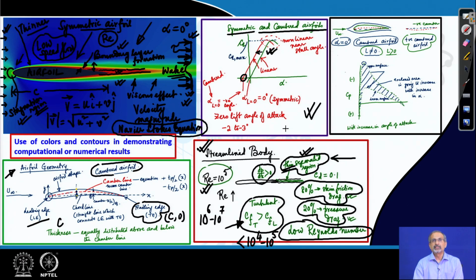If you were to see the pressure distribution on the airfoil section, if that data was made available, then you would see that the upper surface and lower surface pressure distributions would become identical, because the flow seems to be absolutely symmetric about the horizontal axis or about the chord line. So, only when the symmetry breaks about the horizontal line, there is a difference in pressure between the upper and lower surfaces, and then there would be a normal force generation.